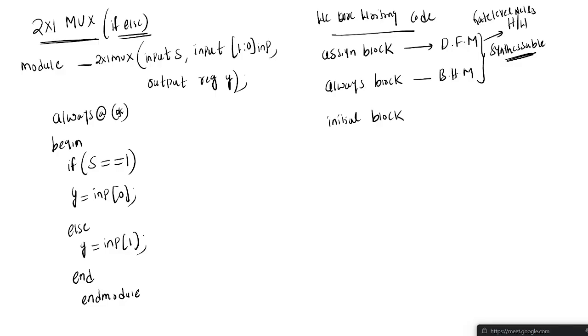The initial block is non-synthesizable. By using the initial block, we cannot convert your code into hardware. Where do you use the initial block? In test benches.